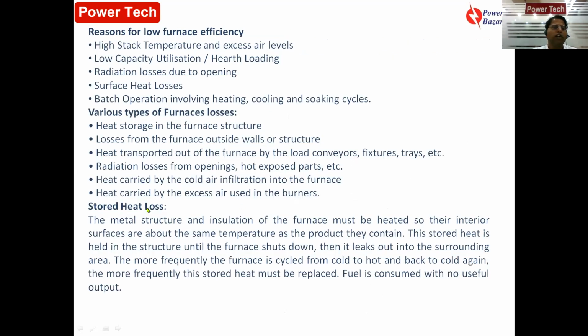Now, what is stored heat loss? Stored heat loss is basically heat stored in the furnace structure. That means the metal structure and the insulation of the furnace have to be heated first. Unless it is heated, it cannot do its working. So you require some heat energy to heat the metal structure inside the furnace and the insulation of the furnace.